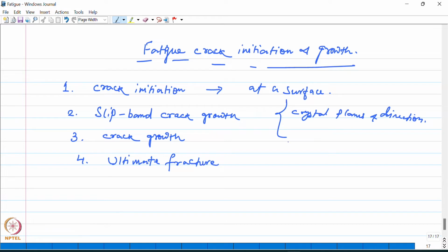However, slip in fatigue is not as widespread and uniform as in static deformation. So in fatigue, while slip lines will be observed in some grains, other grains will be free of such slip. These slip lines generally form during the first few thousand cycles of stress, and during the successive cycles, slip bands form.